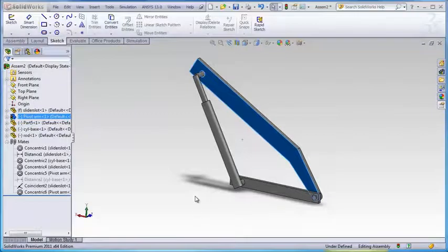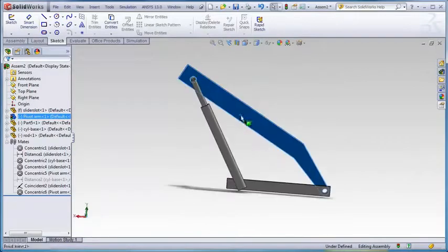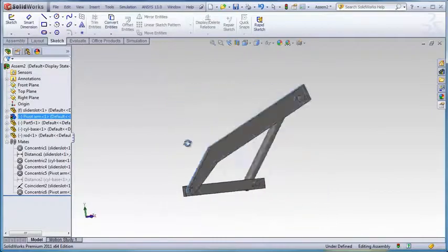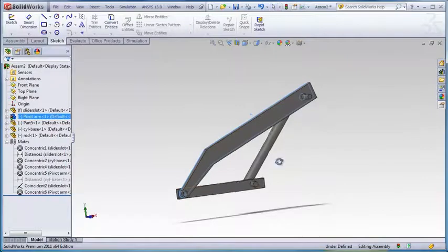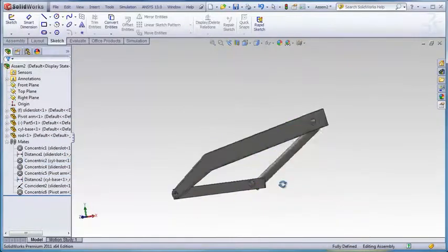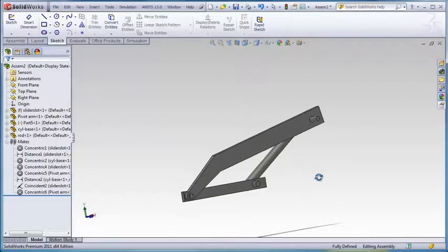Okay, we're going to do a rigid dynamic analysis in ANSYS Workbench 13. We're going to start with some SolidWorks geometry, a mechanism that we've got. Real simple. It's not really a real-life problem, but it's done so you can best see how the software works. So we're going to snap this back into position. The big deal here is you typically want to start out with some geometry in a position that might make sense from a reference standpoint.